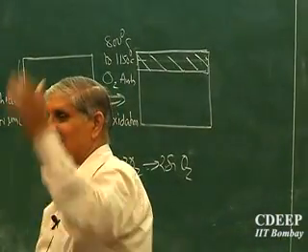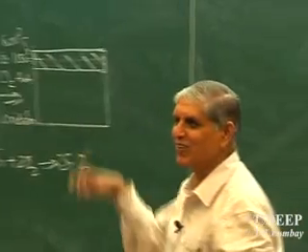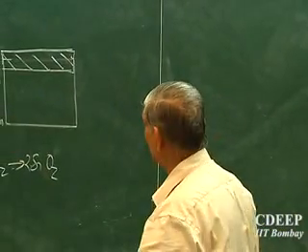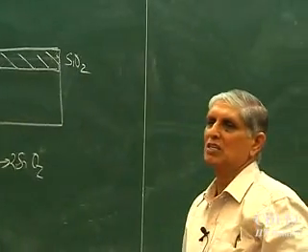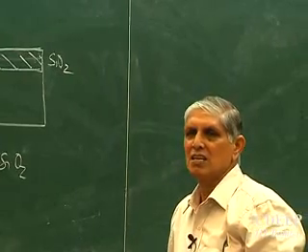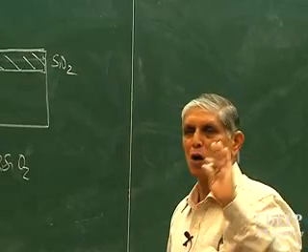The density of SiO2 and the density of silicon are not the same. Is that clear? So when I grow this, roughly 0.5 micron of silicon will make 1 micron of SiO2, because of the density difference. So half of the silicon, 0.5 consumed in silicon, will grow 1 micron of oxide. This is for the sake of people who will never learn technology, I thought I should show you. Otherwise we don't show it every time, we just grow on the top. Okay, so I have an SiO2 layer. So the first processing step is to convert silicon into silicon dioxide, which is now available for blocking impurities.